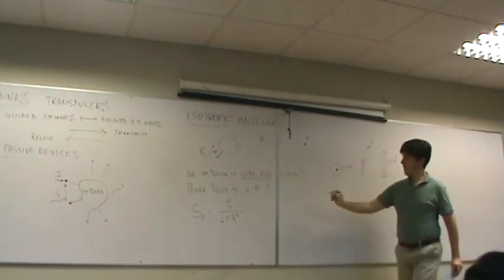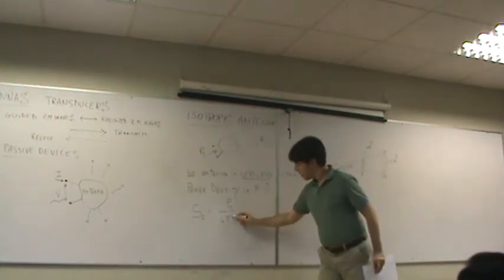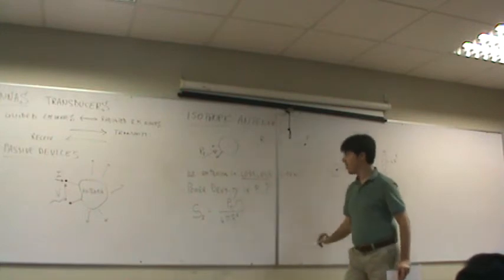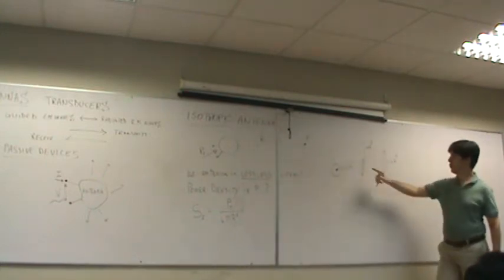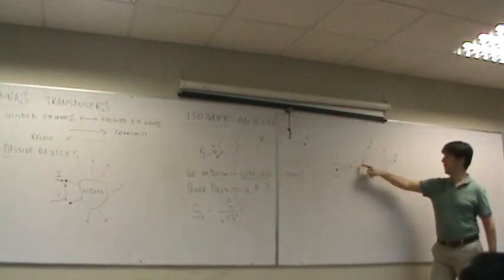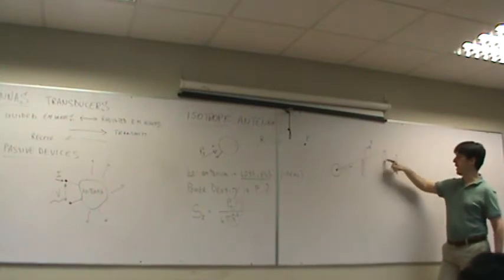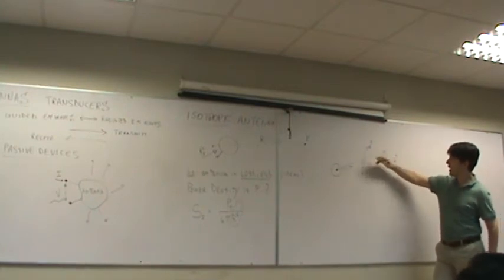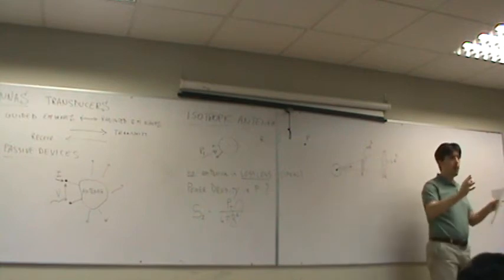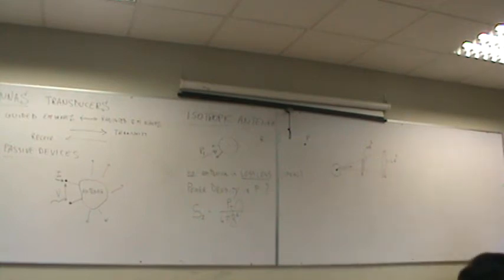So this dependence is simply due to the fact that the further away you go from the antenna, the larger the area where the power is spread. So it's a pure geometrical spreading mechanism. There is nothing electromagnetic in it.